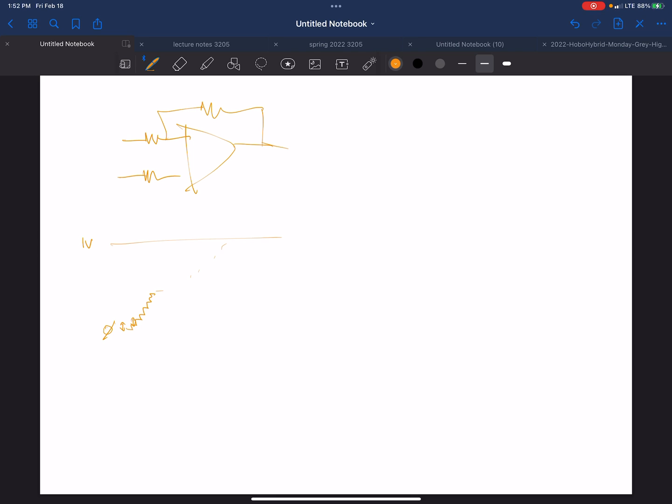So here, one problem with this obviously is the noise, right? Because these steps tend to be small. If I have a 1 volt power supply for a binary function, I have 1 step, 0 or 1. Here I have 128 steps between 0 and 1, so I'm not good at doing math here, but we're talking about maybe 10 millivolts or something in these steps.